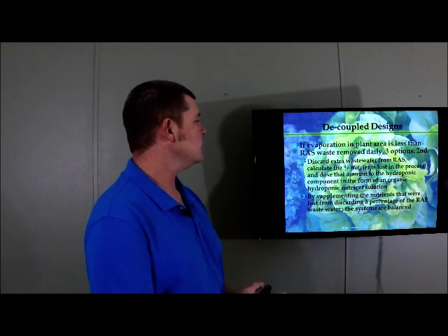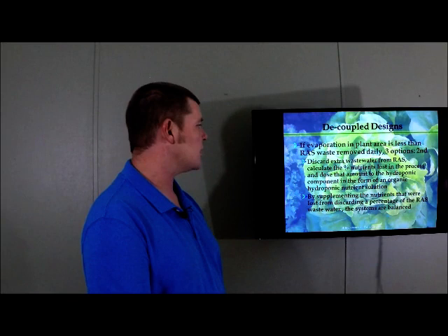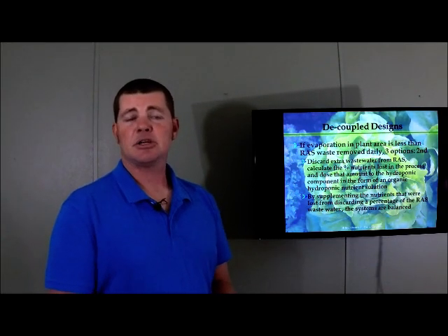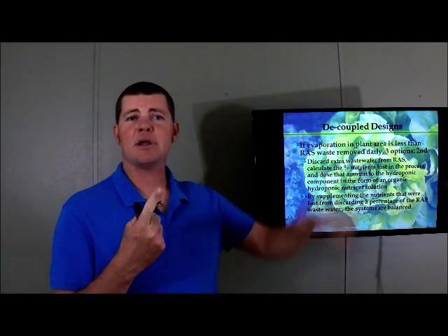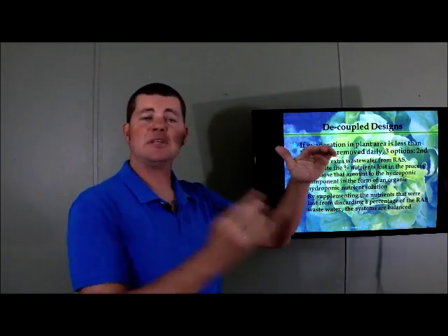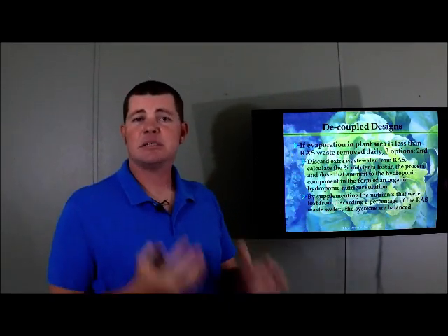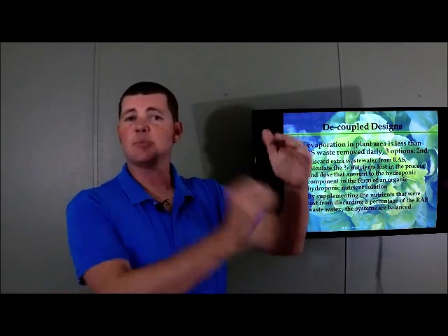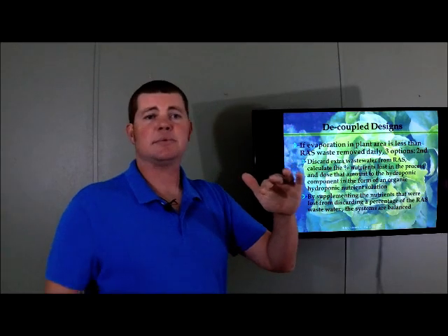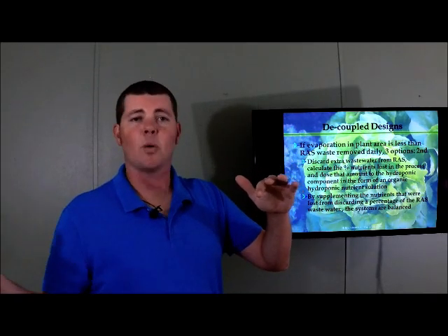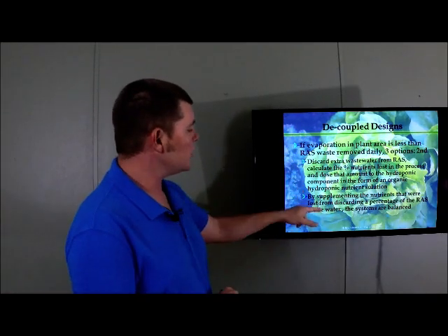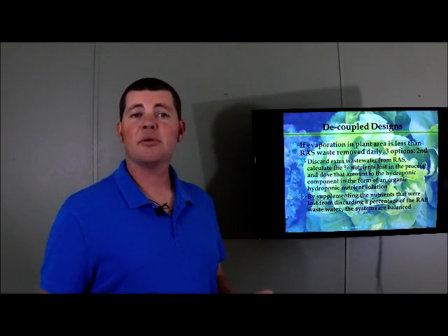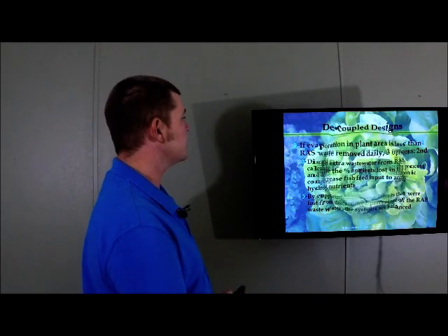By supplementing the nutrients that were lost from discarding a percentage of the RAS wastewater, the systems are balanced. So in the first means, we evaporate water to still accept all the discharge from the RAS, and it's balanced. In our second way here, we can't accept all the discharge from the RAS, so we say discard 20% of it. Well, that 20% of nutrients that we needed, we make up by supplementing them in the form of an organic hydroponic fertilizer.